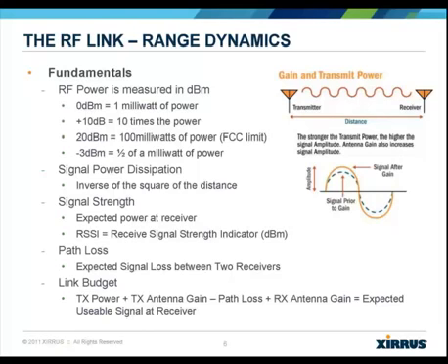RSSI stands for Received Signal Strength Indicator, basically the energy level at the receiving antenna. Wi-Fi connections can be made with signals as weak as -90 RSSI, but Xeris recommends designing your network so all areas will have a signal strength or RSSI value of approximately -65 or stronger. This is especially important if handheld devices like tablets or smartphones are to be supported.